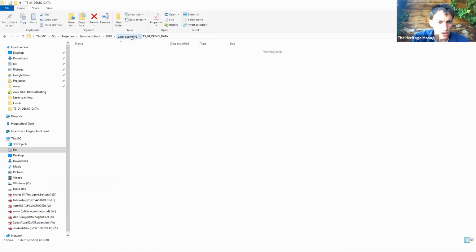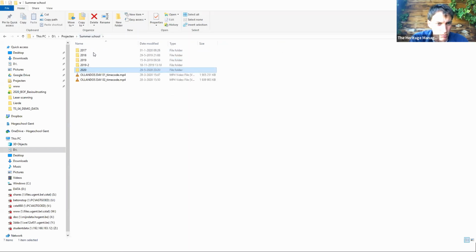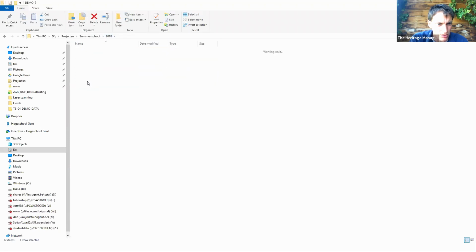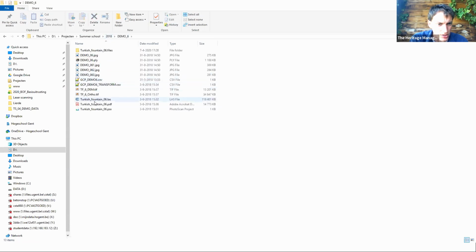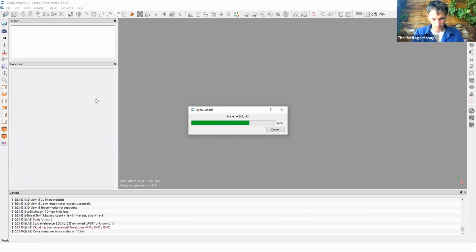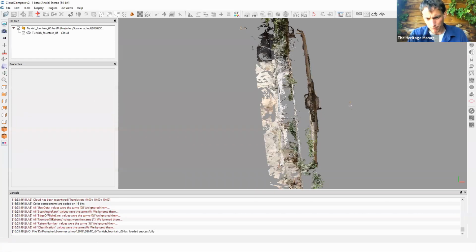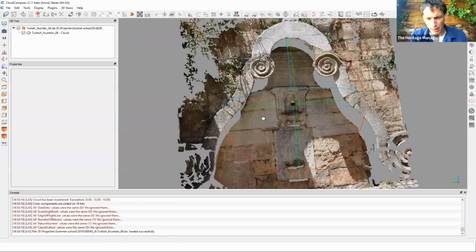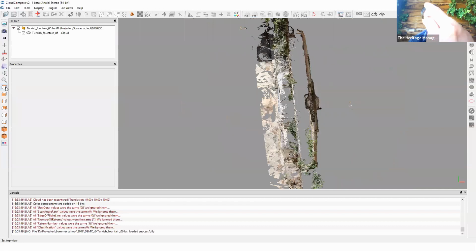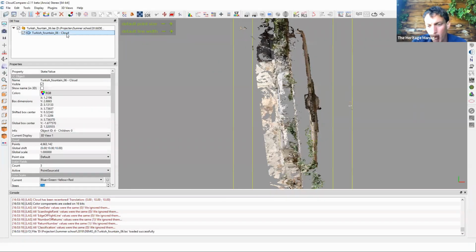So if I have a randomly oriented point cloud, let me find one. I will take this one. If this is my point cloud, and I want, for example, to make an architectural map of the frontal side of this fountain, you have several options. In that case, it is preferred to have my blue Z axis pointing towards me, in this direction. And in that case, I actually want to rotate my point cloud.